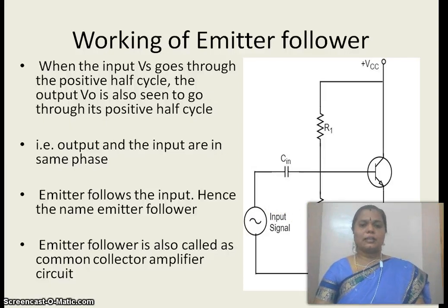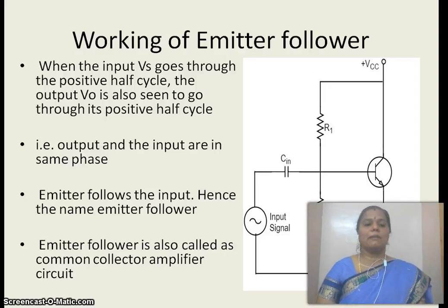So to summarize all the topics related to negative feedback amplifiers, we started with feedback and types of feedback, discussed the voltage gain and the advantages, and ended with two illustrative circuits where we can make use of negative feedback. And to conclude, though the gain with negative feedback is low, it finds advantage in many electronic circuits because of high input impedance and low output impedance.